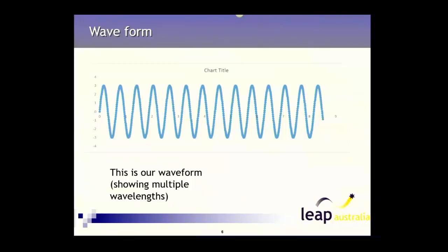You need to make sure that your time step is small enough to capture the highest frequency that's in your signal. So if you have a step excitation, so it might be an impulse load onto a structure, that will excite all of the natural frequencies at the same time. So all of those frequencies will go into the response of the structure.